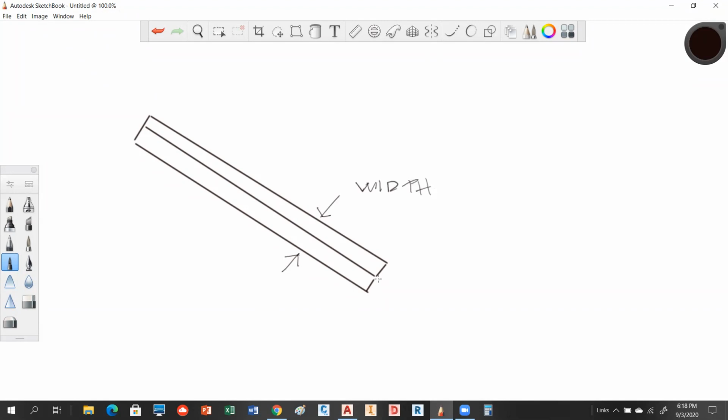They also have something in a polyline called a half width. So that would be this dimension. That would be my half width. They're essentially the same animal. It's just one you define with a half and one you define with the whole, kind of like with a circle. You can either talk about its radius or its diameter. The other thing about a polyline's width is that this edge really doesn't exist on that polyline. Really, the only geometry that you have existing is that embedded line on the inside.